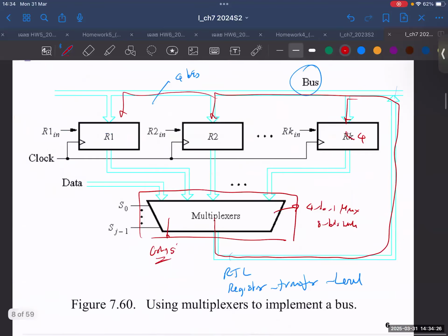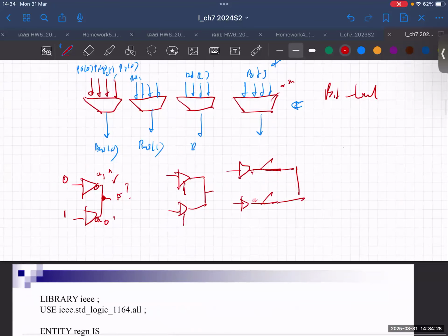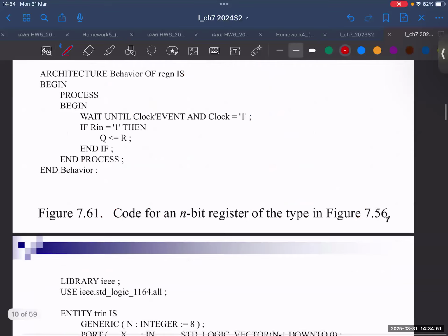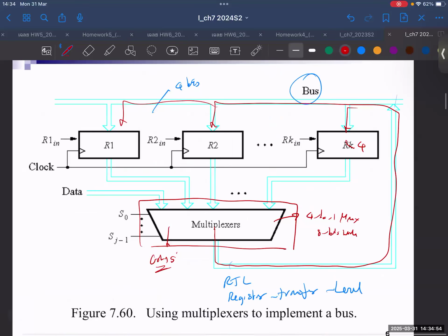the architecture will look like this: you have a central bus, right? And everything is connected to it with tri-state buffers. So if you have a new device, you just put it in there. It's very simple and very easy to expand, right? That's why they use the bus architecture. And with this one, the only thing is you don't have to worry about collisions. It's always determined.